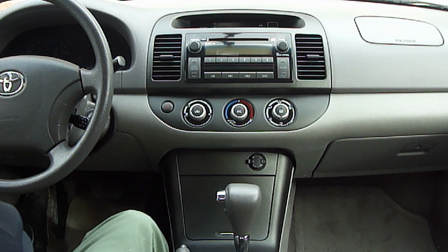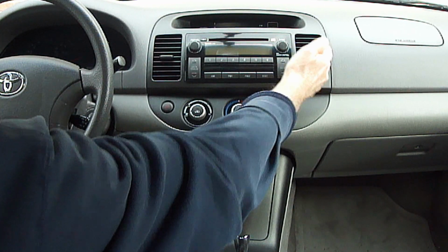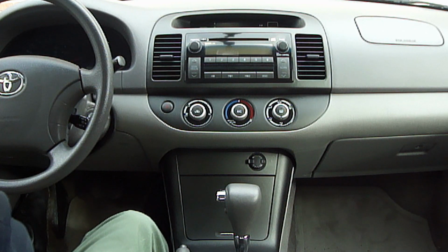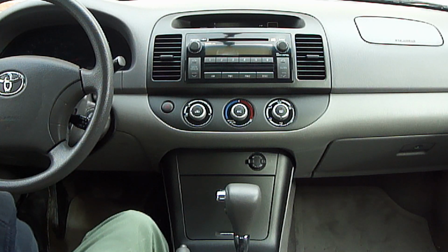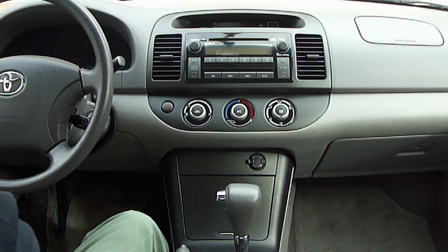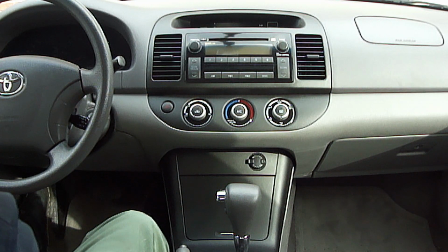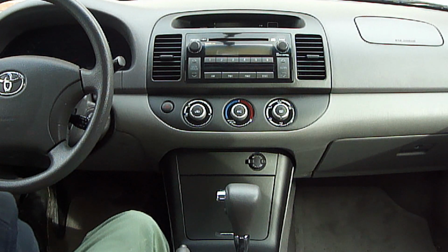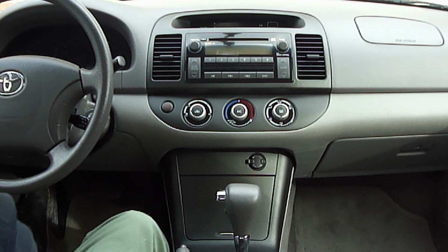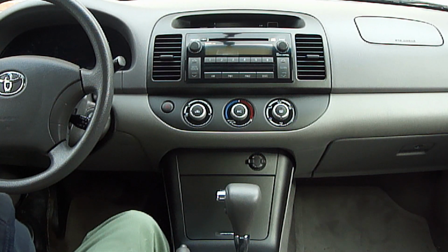The sensor is commonly located on the passenger side and on the side of the condenser that's closer to the rear of the vehicle. Depending on the make, model, and year, you may be able to gain access to the sensor fairly easy by looking underneath the dashboard or behind the glove box, or by removing a few plastic panels, or by removing the radio. Other vehicles will require the dashboard to be removed partially or completely to gain access to the sensor. This can be very complex and time-consuming and may require specialized tools.